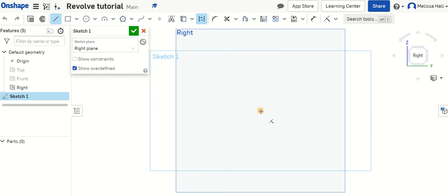Now, if I hover over that center line, you can see that that line is a dashed line, and that shows me that that is a construction line. So I'll just add in 2 construction lines to start the drawing off. Once I've added that second construction line, if I hit escape on the keypad, that will make sure that command is no longer attached to the mouse.